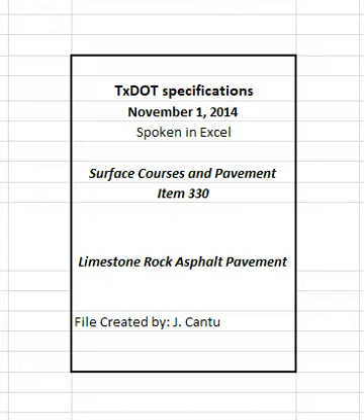The engineer may allow placement to continue for no more than 1 day of production while the contractor takes appropriate action. Suspend paving if the problem still exists after that day until it is corrected to the satisfaction of the engineer. Remove and replace any mixture that does not bond to the existing pavement or has other surface irregularities identified above at the expense of the contractor and to the satisfaction of the engineer.